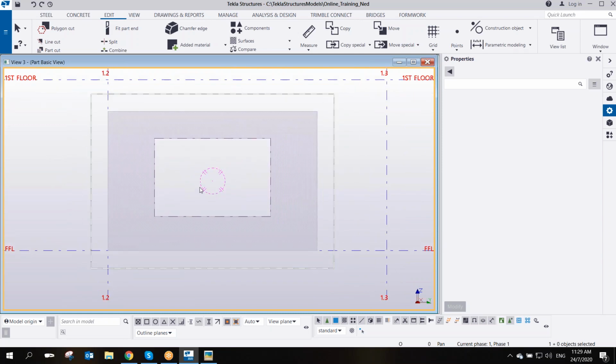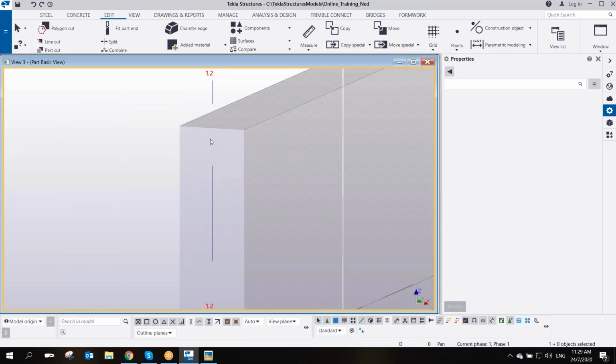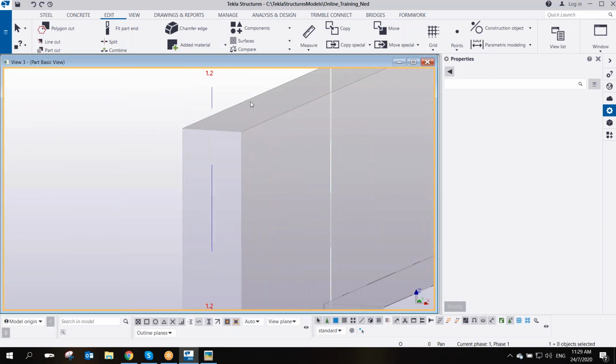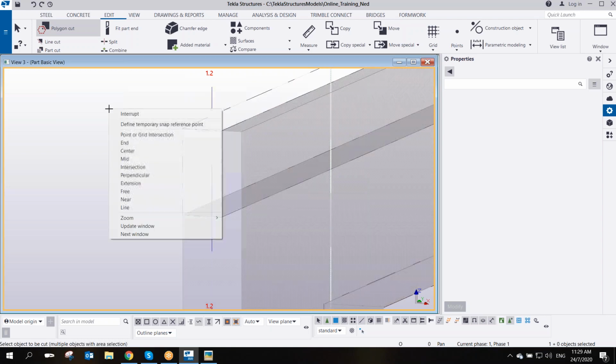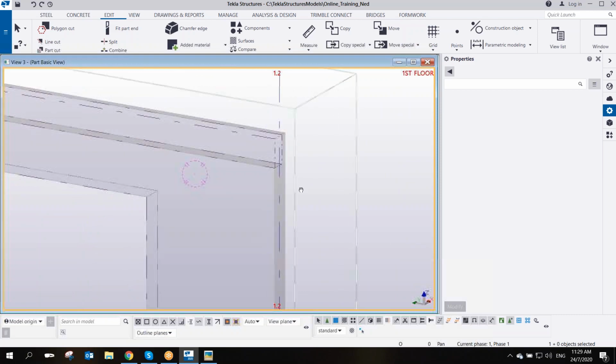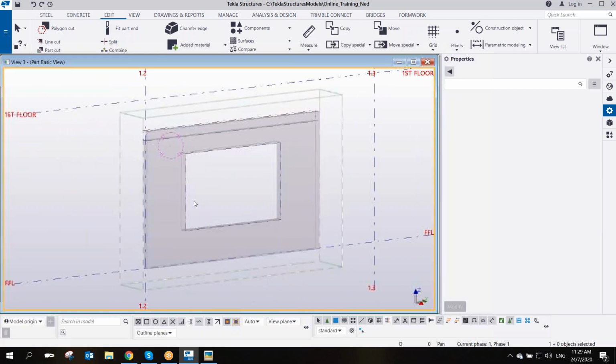Okay, now I can add the cutting here, which is 200 by 100. For the cutting, I'm going to use also my polygon cut. So from here, select the part to be cut, and then 1, and then 100, and then go down 200, and then here 100 as well, and then middle button of your mouse. Then you have now the cutting at the top of the wall.